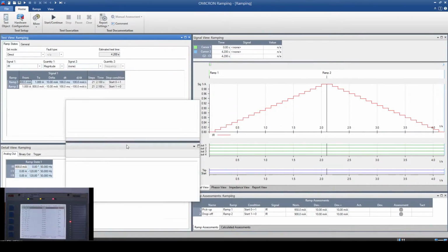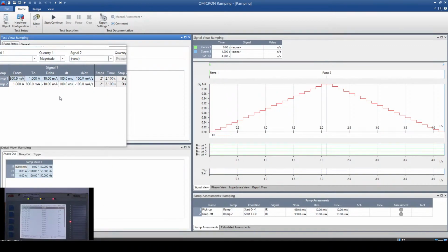So generally for any numerical relay, the pickup and drop off value should be close to each other, but in some cases the acceptable drop off by pickup ratio is around 95%. So the drop off value can be up to 95% of your pickup value.